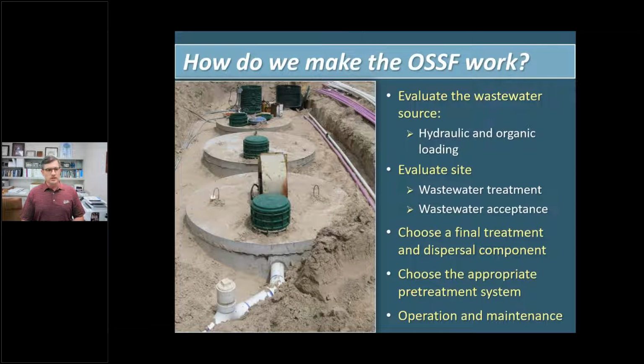But in my mind, I would rather size up a little bit than back. But thinking about the hydraulic and the organic loading, so the amount of water that's flowing into the tank that's going to be treated along with the organic loading that's going to go in. And this is going to be my first plug, and I hope I say it a lot.